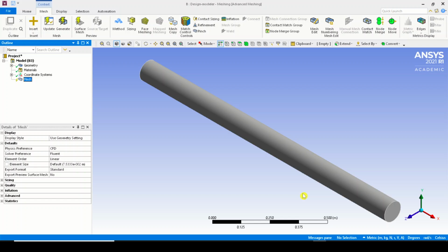We know that all flows in nature are governed by the momentum, the continuity, and the energy equations, right? So the software is utilizing these three equations, along with some turbulence model, solving them on each control volume and giving us results in terms of numericals.